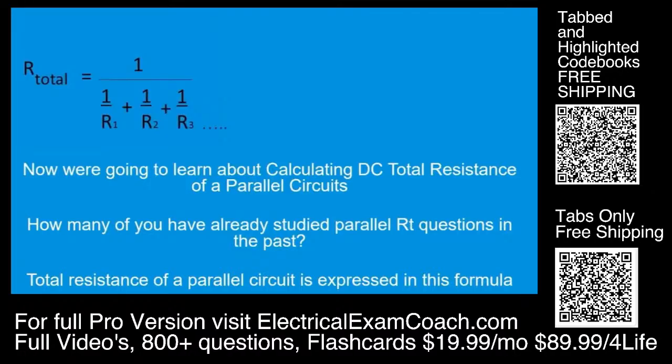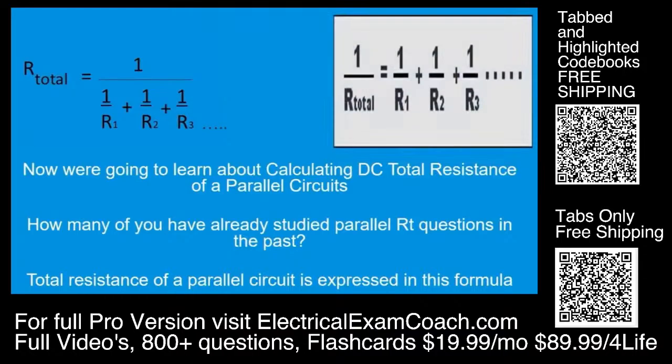To get the reciprocal of a number, you will just divide that number up into 1. What we're going to do is first get the reciprocal of each resistor, then take the reciprocal of that number, and that is going to give us the resistance total. This is another way to look at the formula. The reciprocal of R total equals the reciprocal of each one of those numbers. So that's another way to look at it.